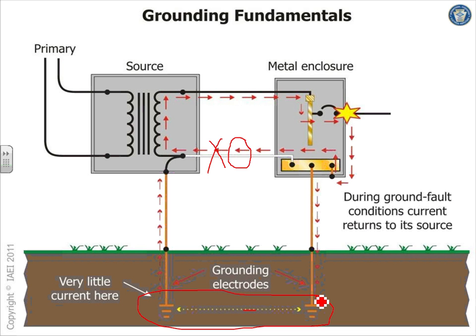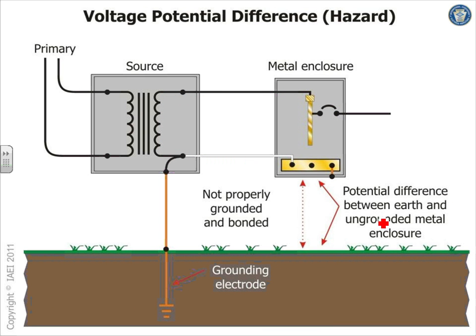It's not approved, but it's kind of a safety factor that you can use. Now what they're saying is, if you don't ground here, there will be high potential between this piece of equipment and this piece of equipment. If you live in an area where the transformer is 100 or 200 or 300 feet away from your house, not a whole lot of potential. If the transformer is, say, 1,000 feet or maybe 700 feet away from your house, you could develop enough potential to be hazardous.